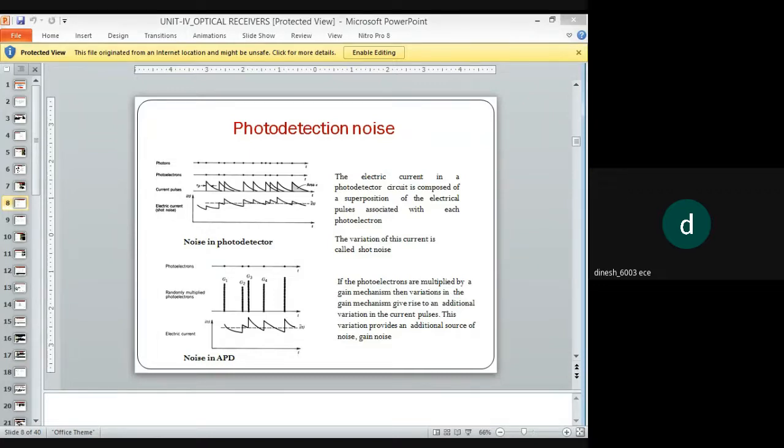The signal to noise ratio for a photodiode and the avalanche photodiode receiver with mean gain M equal to 100 is given at the bottom, where the excess noise factor F is equal to 2. At low photon fluxes the avalanche photodiode has a better signal to noise ratio, and at high fluxes the photodiode receiver has lower noise. So depending upon the application you can choose it.